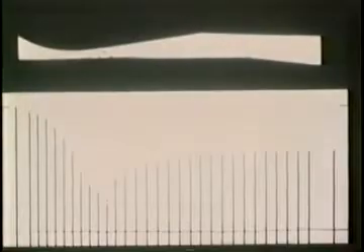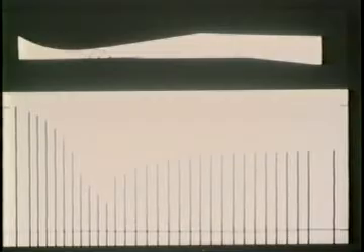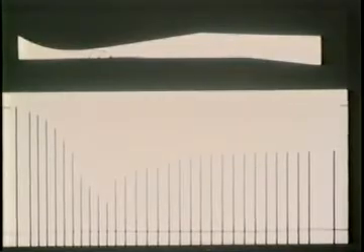So is the pressure distribution, because at first the pressure is decreasing, and hence the velocity is increasing in the diverging channel. After the shock wave, the pressure is increasing, and the velocity is decreasing in the same diverging channel, showing subsonic flow. The supersonic region ends at the shock wave. Because there is no upstream influence in a supersonic region, the Mach waves are steady. But the shock wave is not. In fact, the shock wave in this channel turns out to be not a single normal shock, but a complicated system of non-steady oblique shocks.